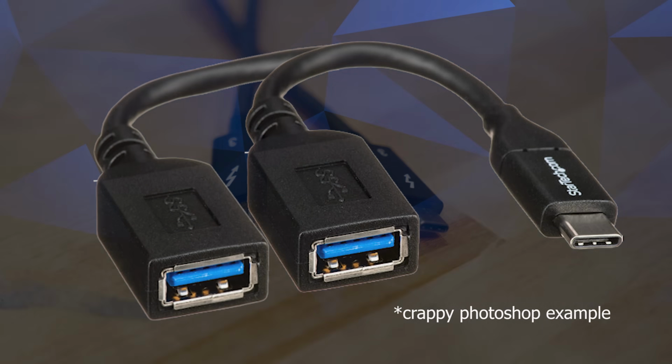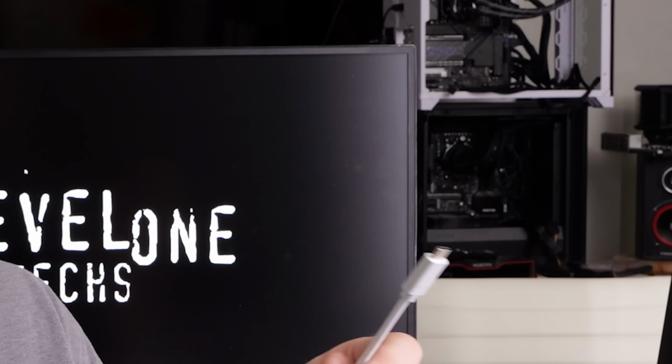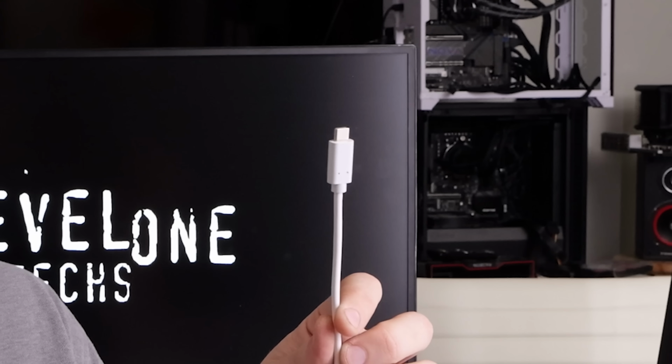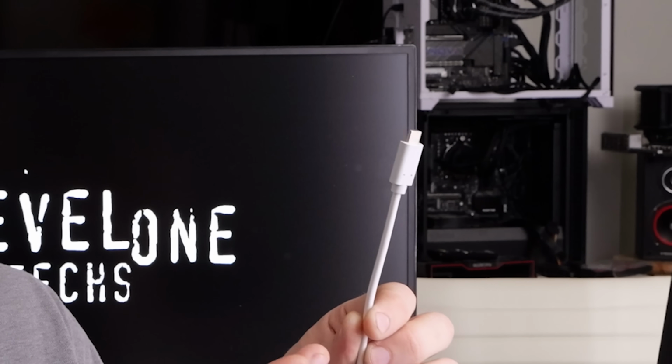Some of you have even seen these funky cables you can get at some of the markets in Taiwan where it's a USB-C into two Type-A. And all that cable does is take the connections on the top and the bottom part of the port and route it out to two different USB ports. Not all USB Type-C ports are implemented that way on motherboards, but a lot of the time to save costs and complexity, that Type-C header really is two Type-A ports that are wired to the top and bottom half of the cable, but you only use one at a time. Not everything is that way.